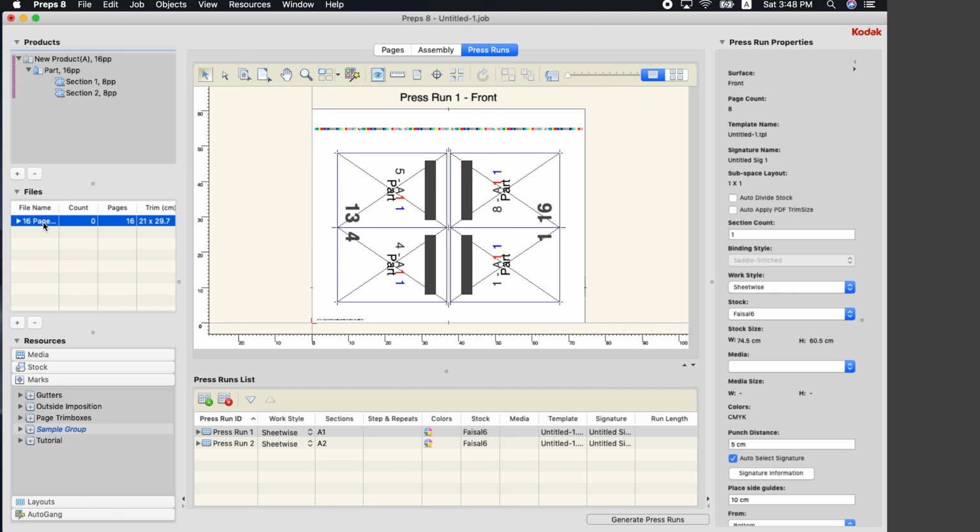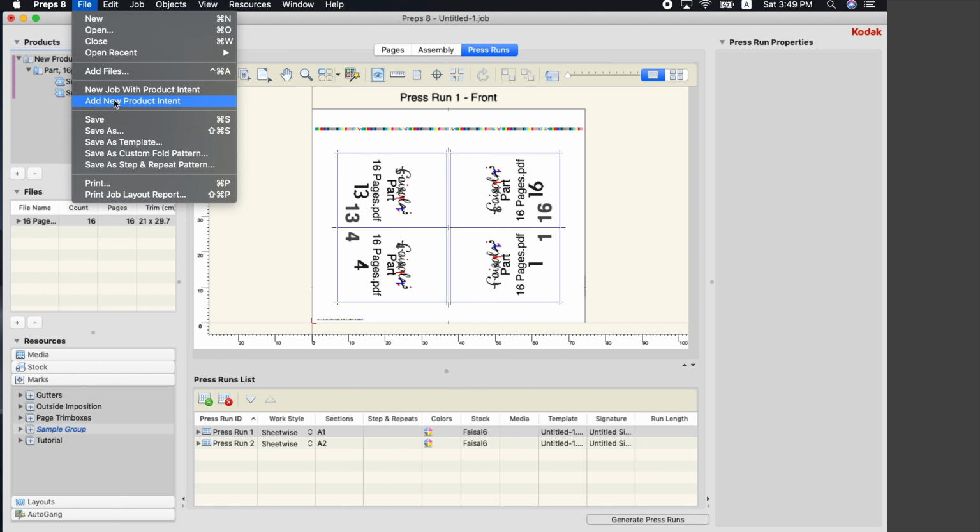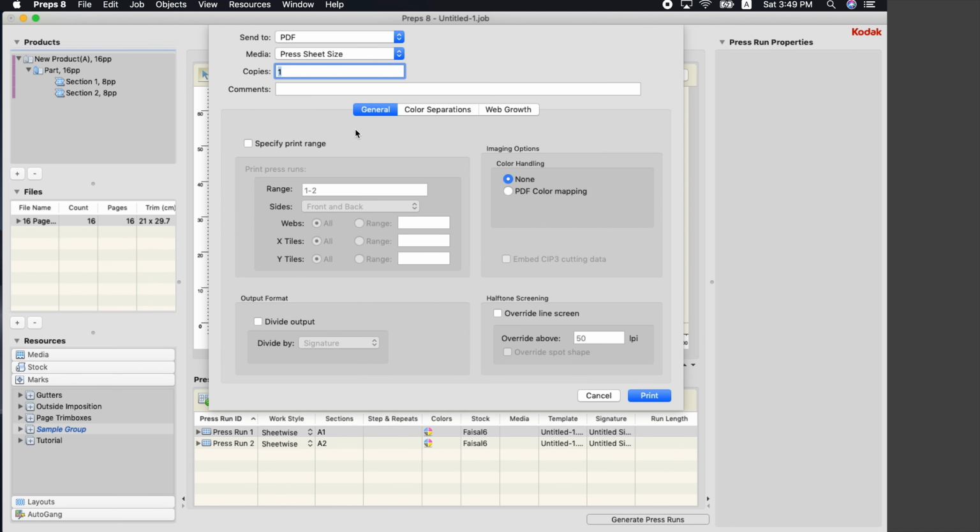Of course, he definitely understands that it's a booklet and all that, so I drag it like this. Now that's it. I only have 16 pages that have been distributed in the booklet system. Let's export them or print them as a PDF. I go to print, as I explained, I go to PDF and I print, and here I name it F3.